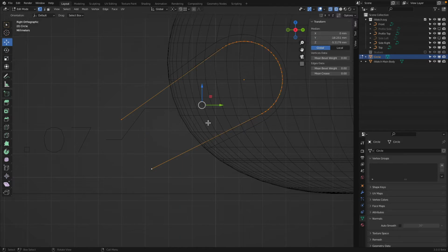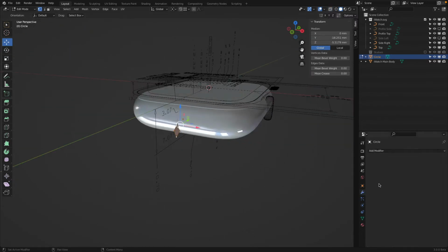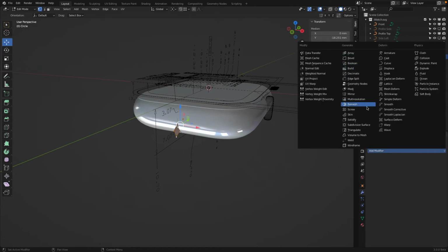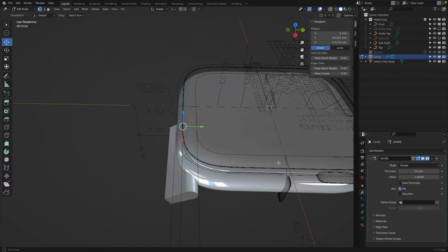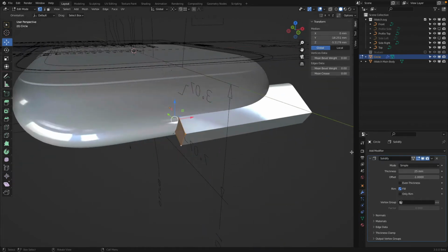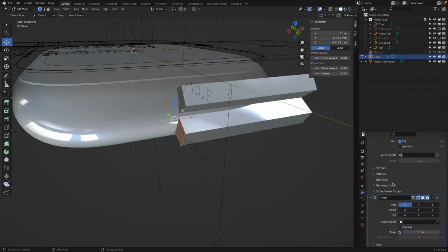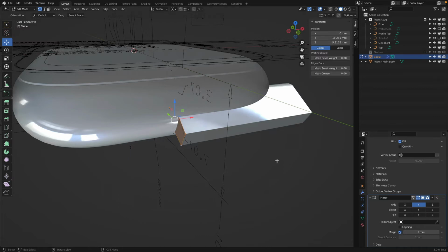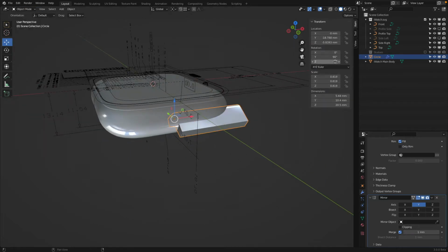So actually A F, A select everything, F fill. This is at the center, which is fine. So we can give this a solidify modifier till it sticks out like this. Very nice. Then we can give this a mirror command along the y-axis. But why doesn't it do it? Let's see. Oh, it's rotated and has a scale factor.